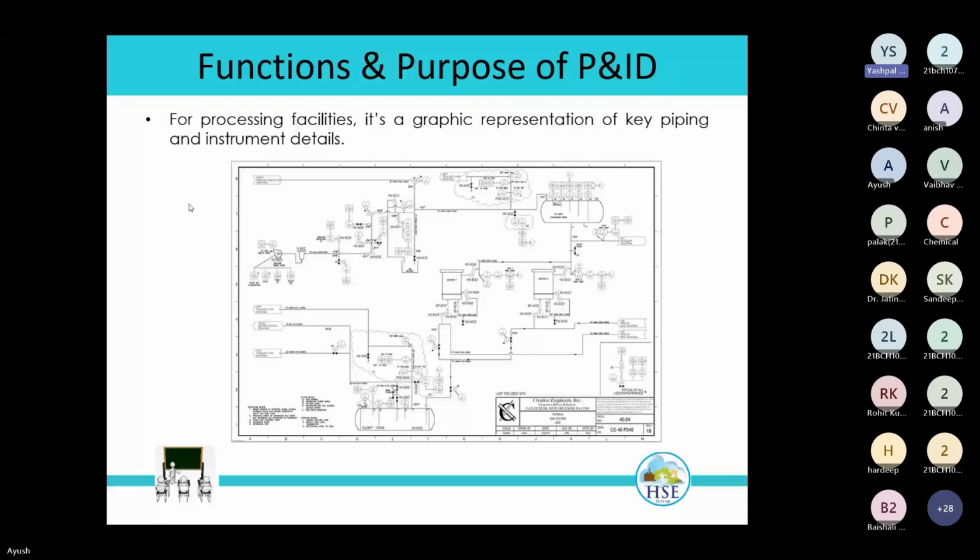Through the P&ID, the risk assessor can understand the process, can find out the different details of the process, and they do the risk assessment. So in general, P&ID is a basic tool for all the risk assessments. After the risk assessments, normally if there are some recommendations for changes in the process or instrumentations or logics, interlocks, or some designs, the engineers involved in the design do the changes and then finalize the drawing. So this is actually the chronology for any project.